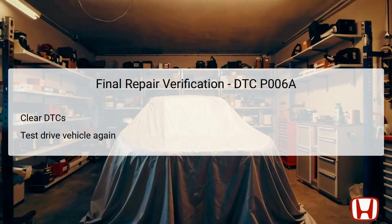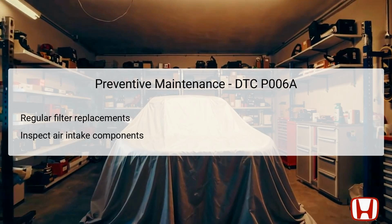Preventive maintenance plays a crucial role in mitigating issues like DTC P006A from arising in the first place. Regularly scheduled replacements of the engine air filter are essential. A clean filter optimizes airflow to the engine, ensuring correct readings from the MAF sensor. Additionally, routine inspections of the air intake components can uncover potential issues before they become significant problems.